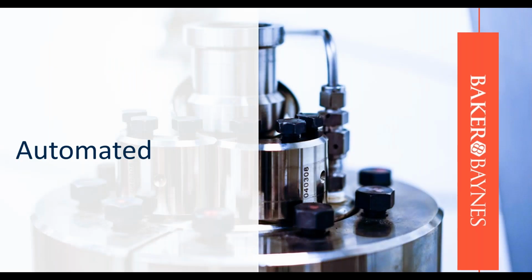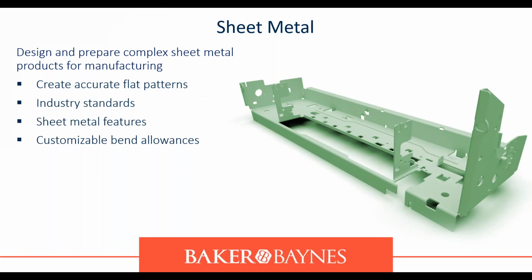Automated. Let's take a deeper dive into the automation tools available in Inventor. The first one is sheet metal. The sheet metal environment inside of Autodesk Inventor enables you to build components with the material and fabrication process in mind. Your designs are controlled by industry standards for bend allowances, corner reliefs, and more to ensure the flattened model accurately represents the finished product.